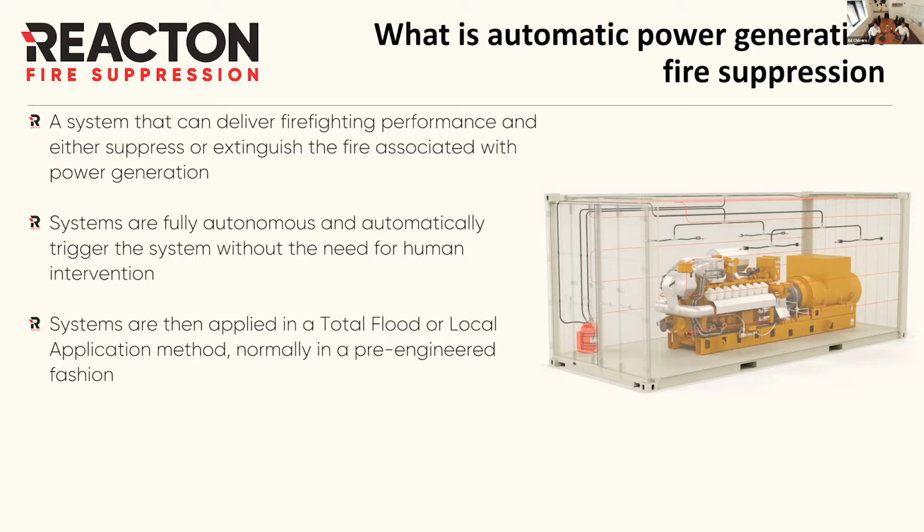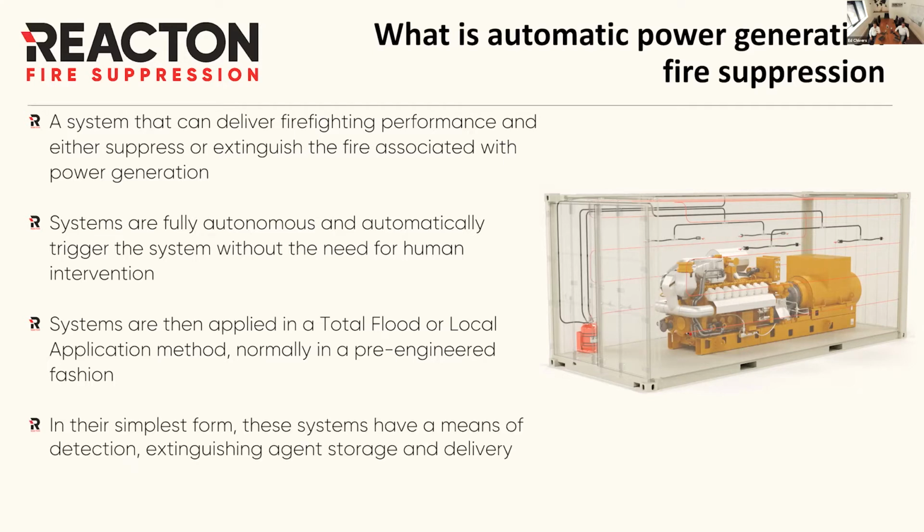The systems that we provide are applied in a total flood or local application method because we're using different extinguishing mediums. They have different ways of being applied. The technology that Reacton uses is pre-engineered, and that means it's a pre-tested package which has a set parameter with it, and if you keep within those limits, you have an approved system. So there are no complex hydraulic calculations or anything like that that need to be done. So they're very well accepted in the industry.